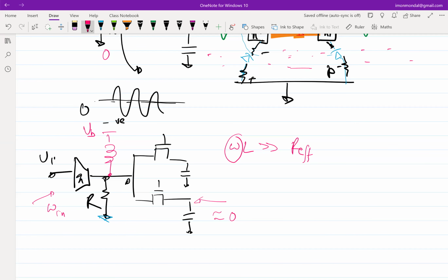At this point, the frequency is omega in. Again, okay, I understand what you are saying, but can you qualify it a bit more? What do you mean at this point the frequency is omega in? Right. So it is before down conversion, right? So what is happening? The current that is coming here is getting mixed and getting down converted here, right? So essentially, you can think the mixer: on the left-hand side of the mixer, you have all the RF components. On the right-hand side of the mixer, you have all the DC components, low frequency components, right?